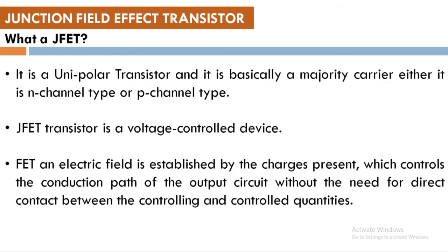Now the nomenclature which says field effect, it's because of the charges that establish an electric field which actually controls the conduction path of the output circuit without the need for direct contact between the controlling and the controlled quantities. This is a very important part in field effect transistors. We will discuss it in the later slides.